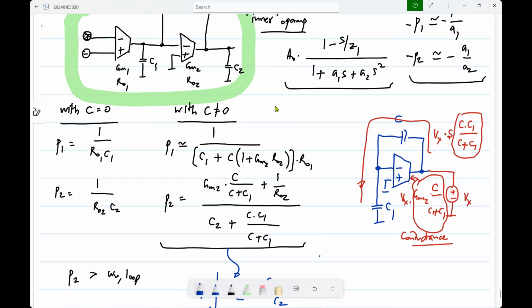We'll see. The transistor level implementation we'll come to later. But the bottom line is, that's why we have divided this into, we first look at everything at the control source level. Now, if you are able to implement the control sources using transistors, you can implement any of these loops. If you understand it at this level, then first of all, there may be a variety of choices for how you realize GM1, GM2 and so on.